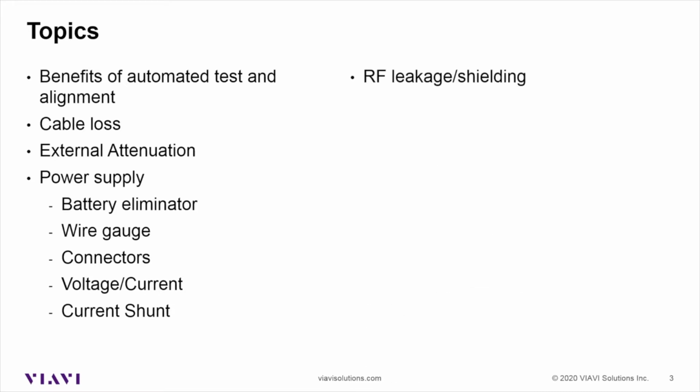Next, we'll talk about some things that can affect our sensitivity testing. When we're testing RF sensitivity, receive sensitivity, we're looking at a very low level. So any leakage that is making its way into the radio can have an effect on our ability to test its sensitivity. So we'll talk about what we can do to mitigate the issues that come with that.